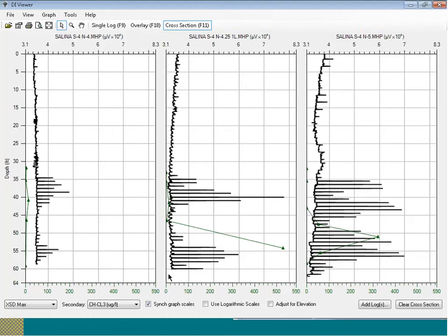Another thing I just want to quickly mention is that when you're performing these logs, you're not going to run standard MIP and low-level MIP in the same log. In other words, run standard MIP until you maybe see some impacts and then switch over. You will run each method and each log type on its own. But if you don't get very many impacts, maybe just a little bit, you could switch over, move over a foot or 2, run a new log in low-level mode, and proceed that way. And this is definitely 2 different data sets.